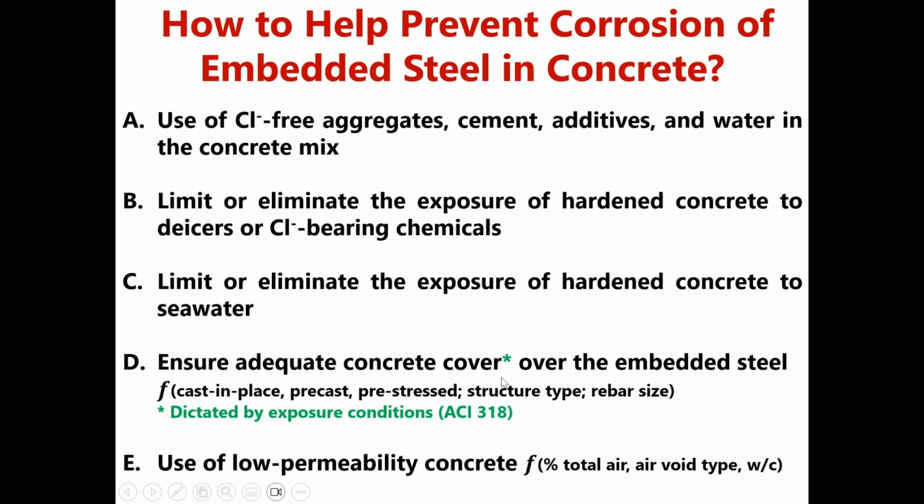And also ensure adequate cover over the embedded steel. Steve can touch on this a little bit more, but the amount of concrete that's covering your steel, from the outer surface of the concrete down to the depth of the embedded steel, that's important. The deeper it is, the longer and harder it's going to take for the embedded steel to be exposed to the water, oxygen, and chloride. And then lastly, if you can use low permeability concrete, that's optimal.